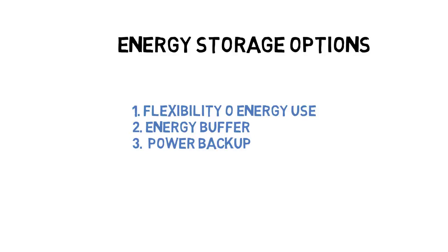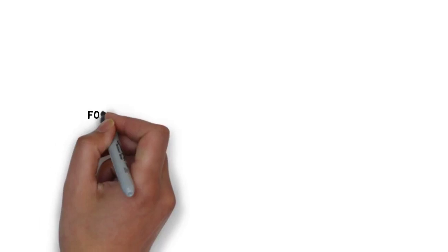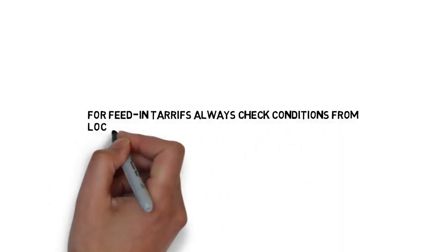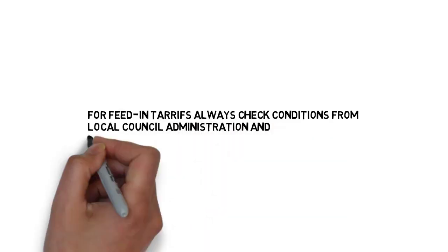Now, it should be noted that if PV installation is being done to make use of feed-in tariffs, then it must be checked beforehand with the utilities or the electricity supplier if they allow systems with battery storage or not.